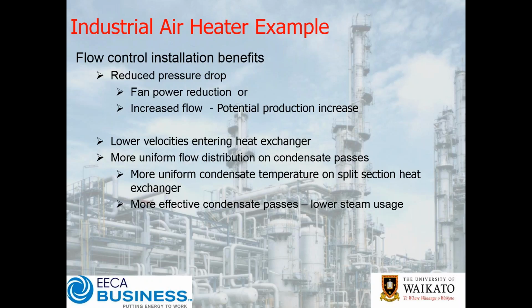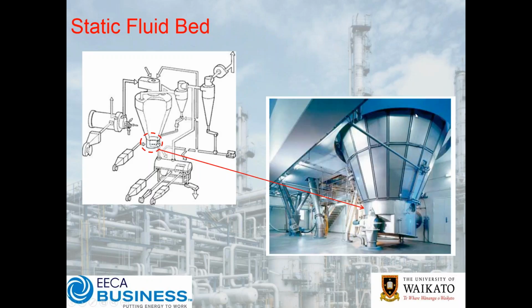But the big benefit in a situation like that is where you would have flash steam going down to your condensate tank and then flashing off and out of the vent. All that steam has been condensed and subcooled, so there's no losses at the condensate tank. So you actually start to really save energy in that there's energy that's not being vented somewhere. So in these cases, the flow-on effects for doing this right can be substantial, and it's not uncommon on an air heater like that. Those savings can very quickly sort of get up into the hundreds of thousands of dollars.